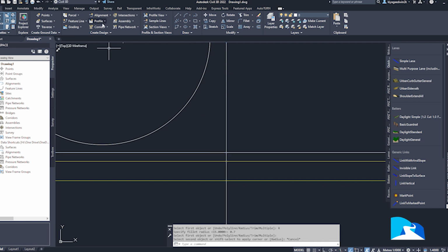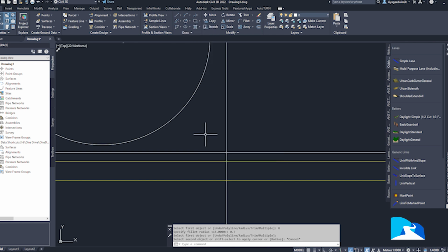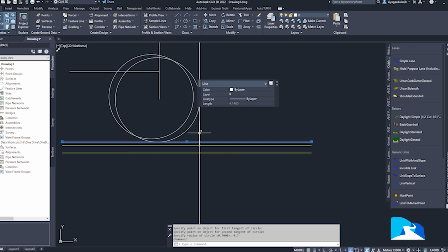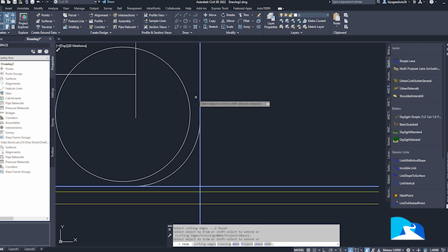Okay, then the other we shall be using is something we call a turn radius circle. Okay, so normally to activate this we press C on the keyboard, which activates the circle, and then we type in T. Okay, turn, then select that point, then select the other point, and then now you can type in the radius. Okay, so let's say here it's 0.7. Okay, we shall use this a lot when we shall be drawing the nose areas, so then you can trim.